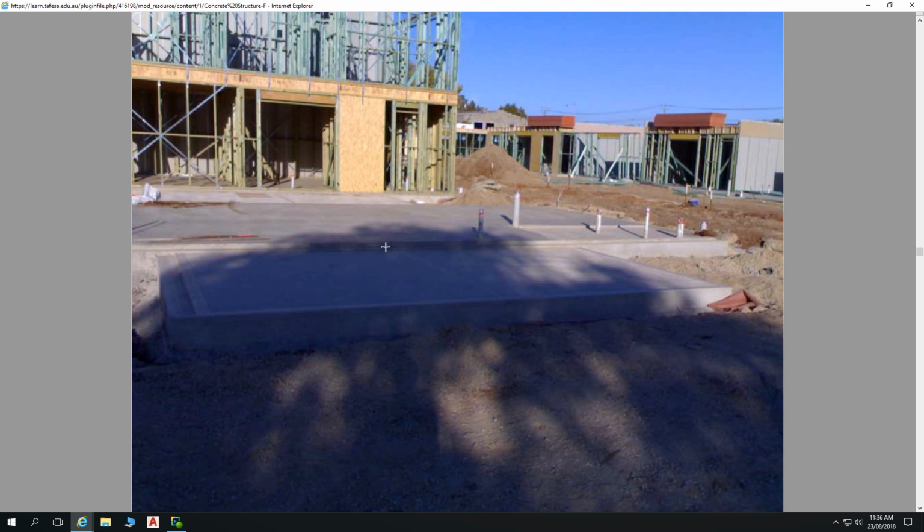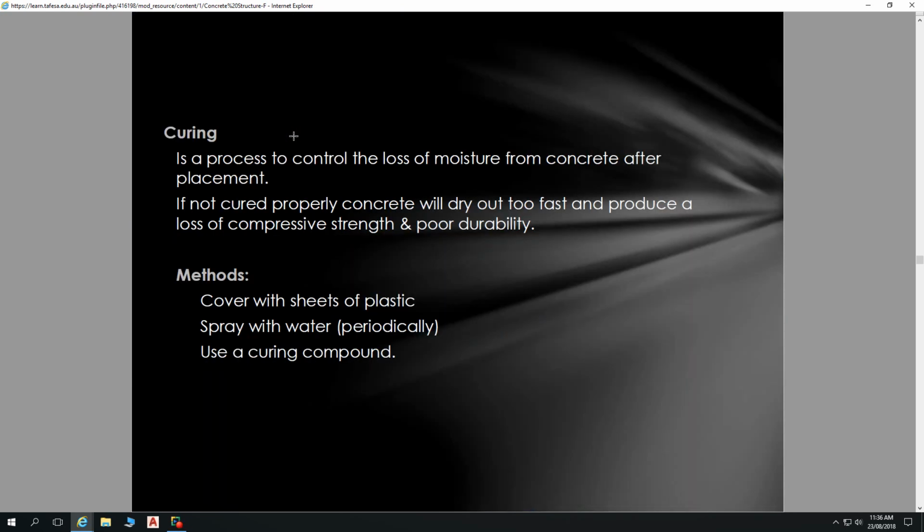Yeah, look, we're certainly less than 600 mil between our top plate there and our window head height. Typically your window head height's 2100, though that window at 2400 is pretty much the standard these days. But yeah, a clear indicator is our rows of noggins there. We'll talk more about noggins and studs and all those bits and pieces later.